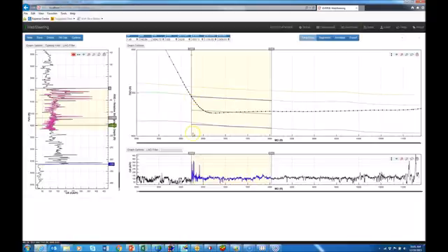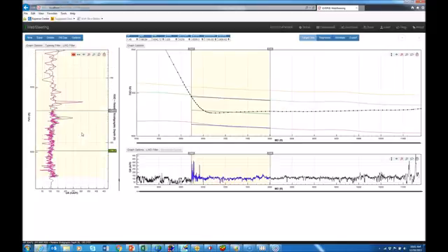Now it starts out with the initial point of the segment, or the dip segment or strat segment, whatever you want to call this, at the intersection of the active surface with the wellbore, and extends out some distance. Now I can adjust the distance out in which I want to do the geosteering by simply clicking on the endpoint, and it adjusts the segment that I'm going to be looking at. Now I'm going to be looking at my initial segment in here, so let's zoom in a little tighter and take the endpoint and adjust it until it matches our type log. Maybe a little higher, something about like that.